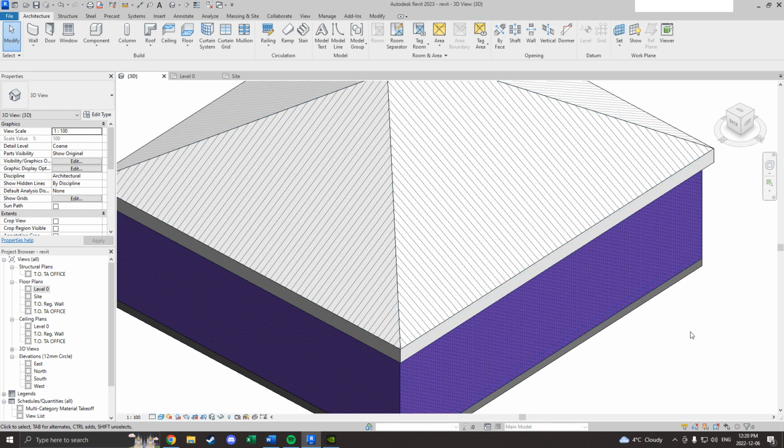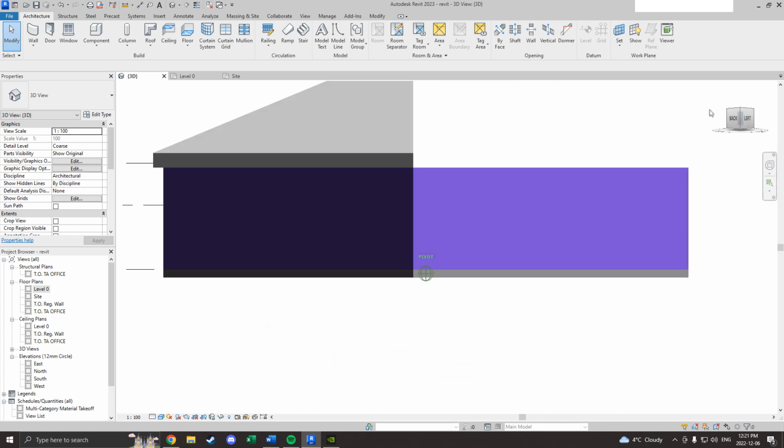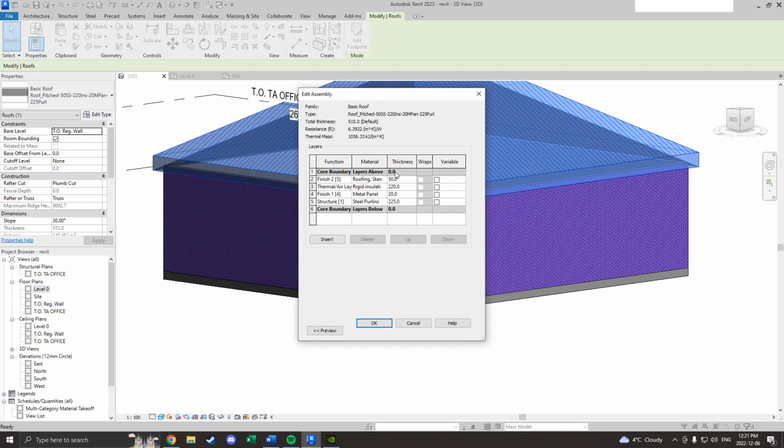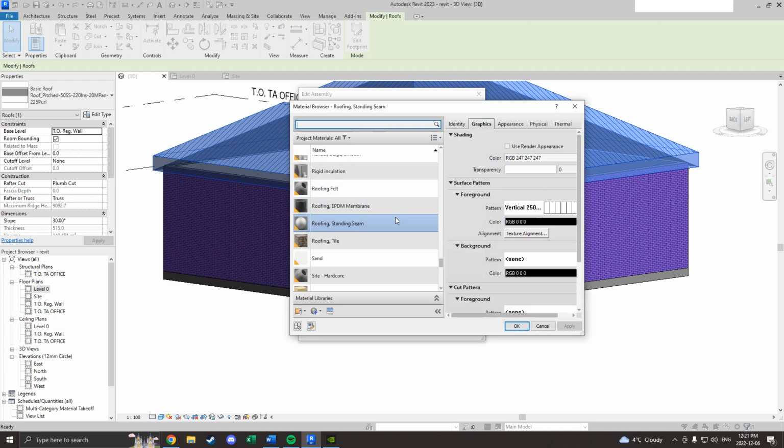So now let's unhide the roof element. Let's save the project. Let's unhide that roof element. So now we can change the roof element. Same procedure. If you see here, the roof element has actually been detailed with insulation, paneling, all this stuff. This is on the top here, so we can change this if we just want to change the visuals. Let's say we want a roofing tile instead of a standing seam metal roof. We can change that there, change the color if we want.